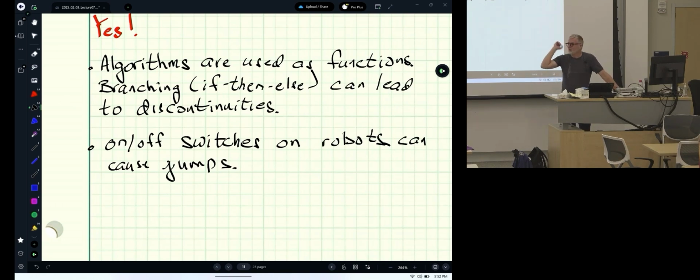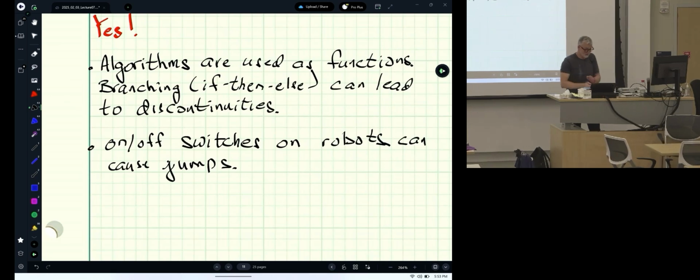So, when you are writing the code for those robots, you've got to be very careful on the startup sequence, okay? Otherwise, you just turn the power on and you enable all of the motors and everything. Who knows what state the last reading of the encoder was that's being input into your algorithm, okay? You need to read it and then have a little ramp that takes you there at a slow rate, which means you need to build in continuity into your algorithm.